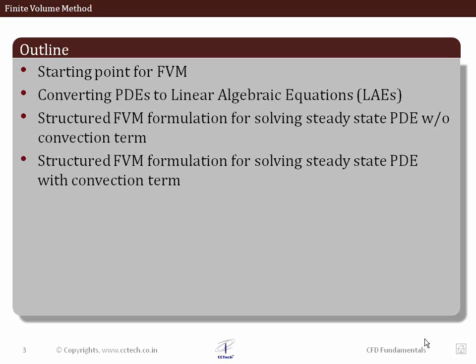Well, we'll go through the starting point for the finite volume method, how it works, and what the strategy is. We'll see how it converts the partial differential equations to linear algebraic equations. Mind you, this is what all numerical schemes intend to do: they convert your given governing equation, which is usually in partial differential form, into linear algebraic equations.